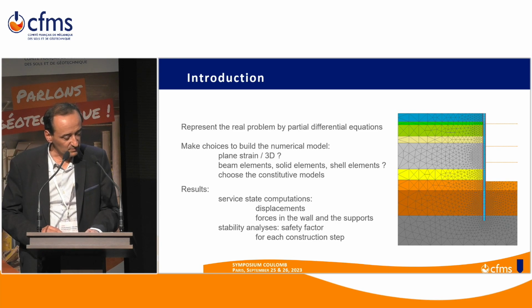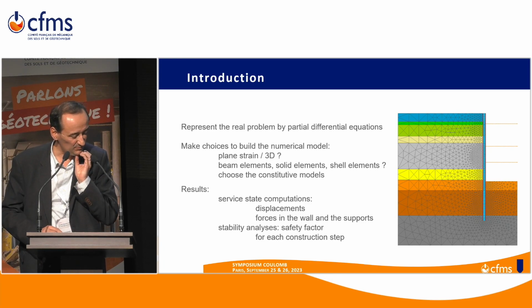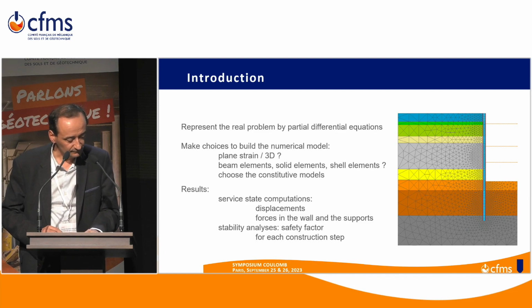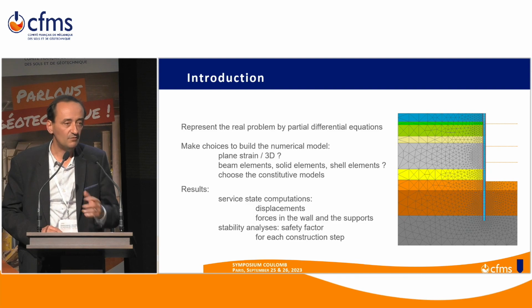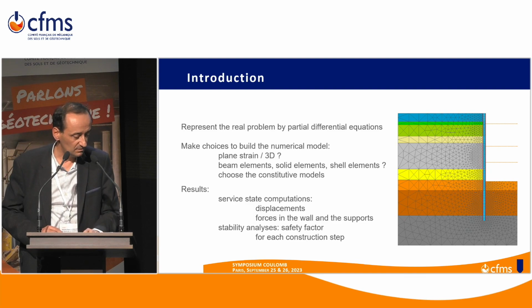And the results we obtain in the case of service state computations is the displacements of the wall and also in the ground surrounding the wall, and also forces and moments in the wall and forces in the supports, the props or anchors. In the case of stability analysis, we get safety factors for each intermediate construction step.